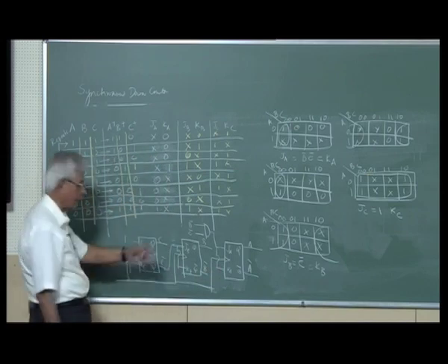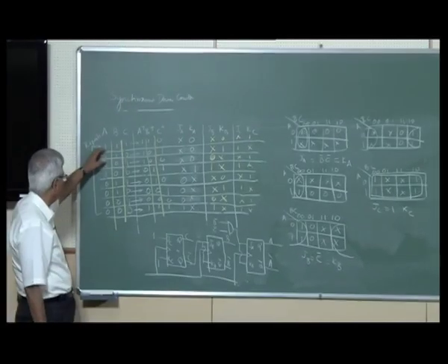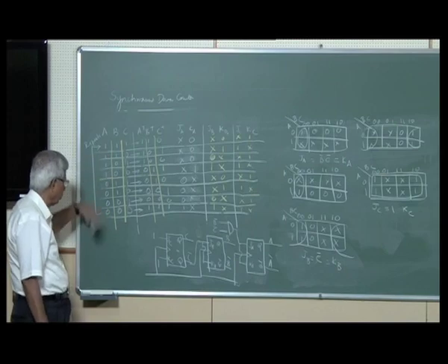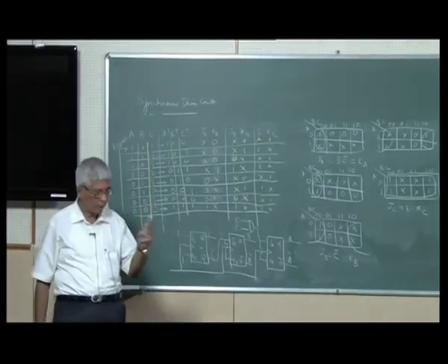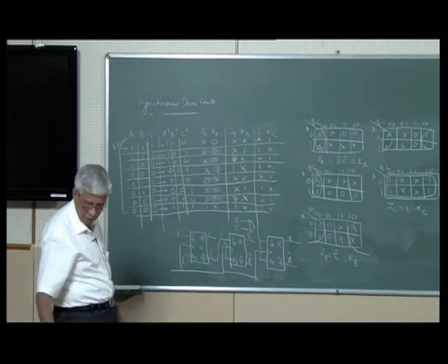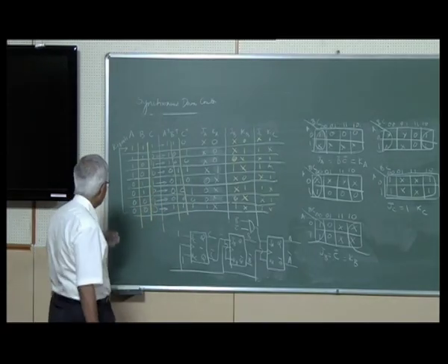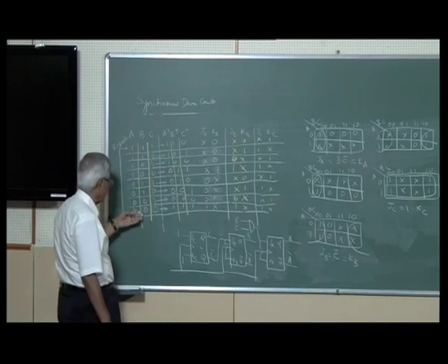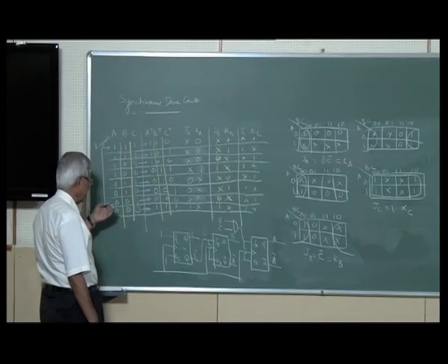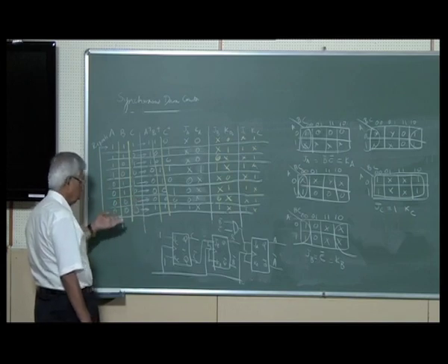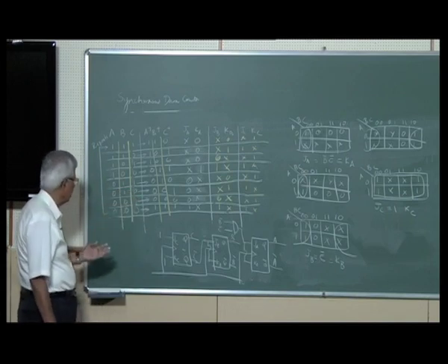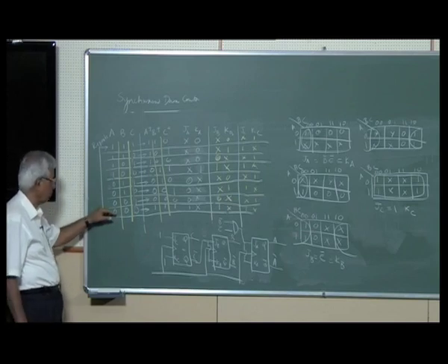This is again a synchronous counter, down from 111 to 000 and repeat. This is using JK flip flops. Now I think what I did earlier with D flip flops also, I must have started here. I should have considered here. So you can make your correction. Whatever DA, DB, DC I drew, you should redo the Karnaugh maps with this as the starting point, not this.